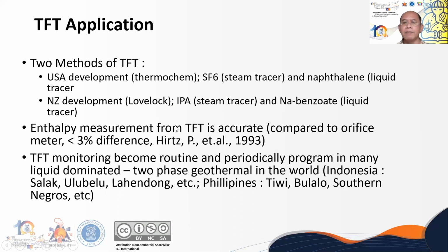The enthalpy measurement from TFT is relatively accurate, with a 3% difference compared with the orifice measurement. TFT monitoring has already become a routine periodic program in many liquid-dominated or two-phase geothermal fields in the world: in Indonesia, Salak, Hulu Lahindong, and in the Philippines, Tiwi, Bulalo, and Southern Negros.